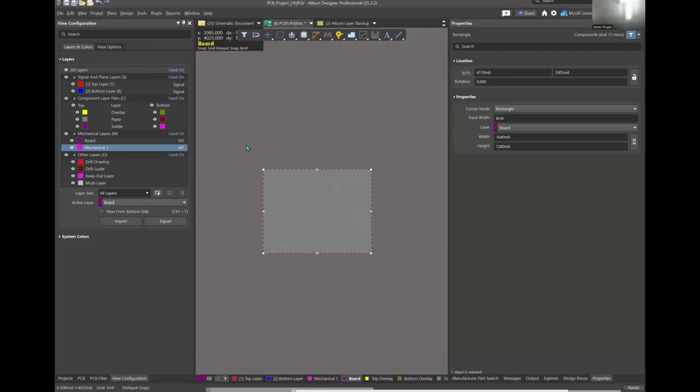So you defined that shape actually on your copper layer, so I would probably not recommend that. But you can move it to your board shape layer by going into its properties and choosing a different layer. So let's move it to the board one. Board is near the top, right?